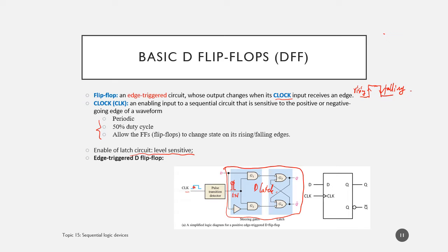If you remember the truth table for the D latch, we have the enable, we have Qn plus 1 the output, and we have the D input, but we don't have to include it here. If enable equals 0, we know the latch is in its no change state, which means Qn plus 1 just equals Qn.